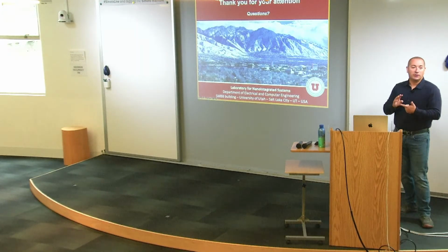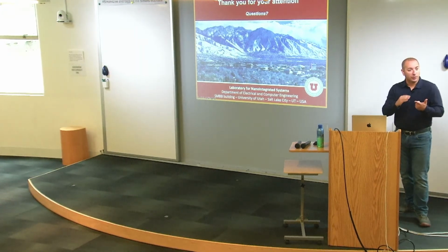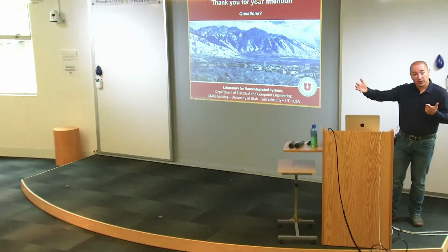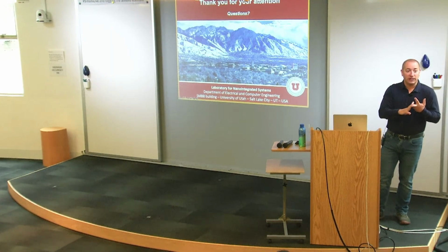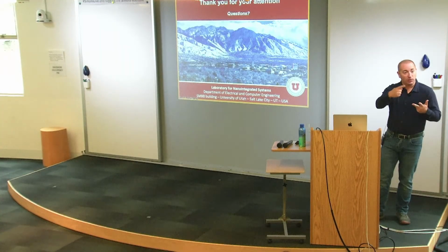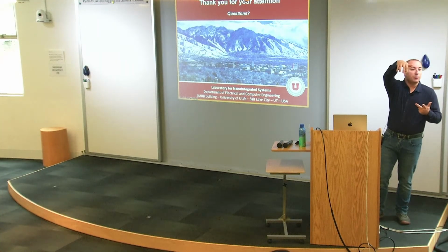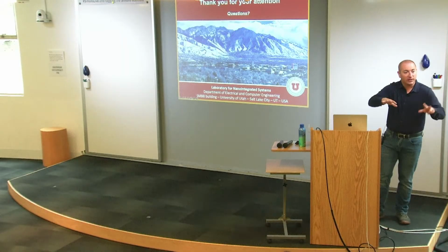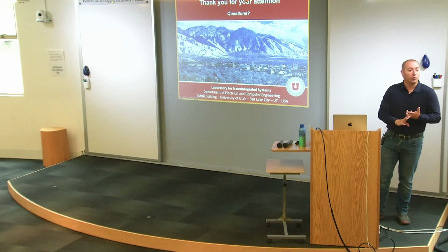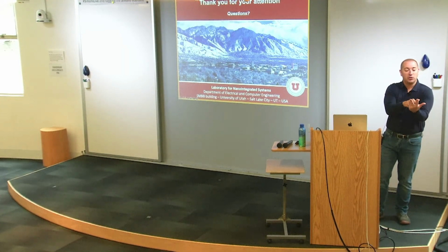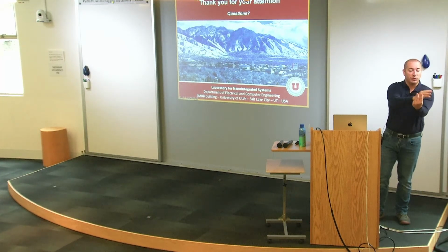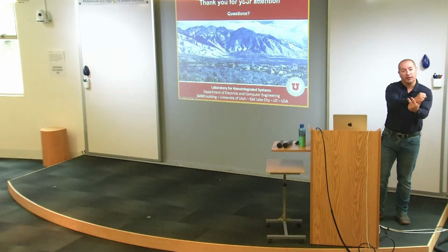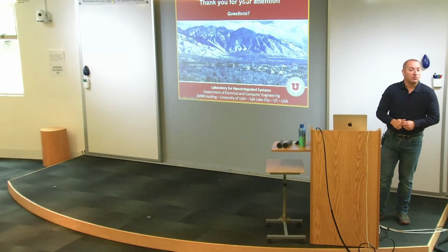The depth of your graph will be a decent proxy for the depth of your logic levels. The activity factor of the edges in your graph, which you can calculate based on the primary input activity factor and percolate through the logic function in your graph, would be a good proxy for power. And then you try to minimize these three parameters, with different weights that you apply to each of them, essentially. Does that make sense?